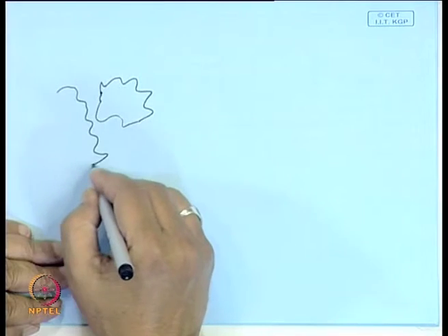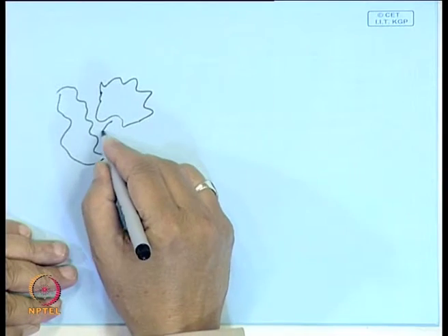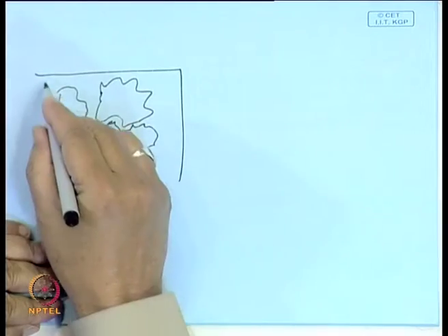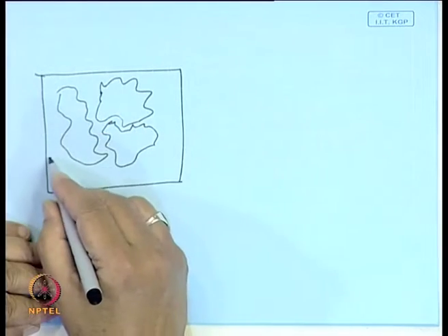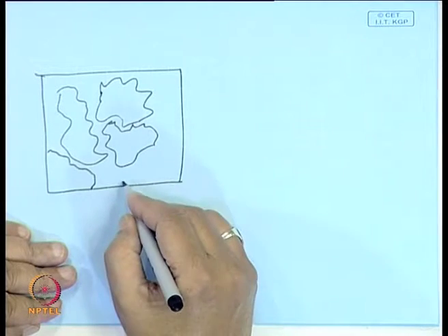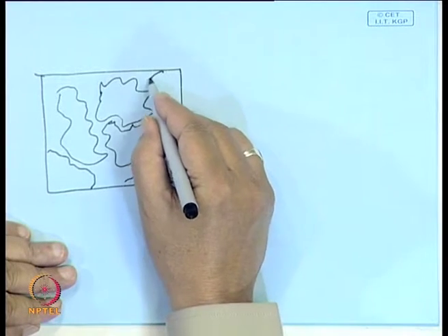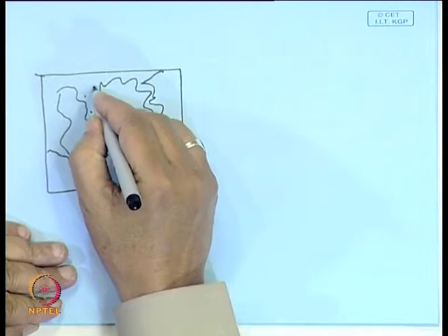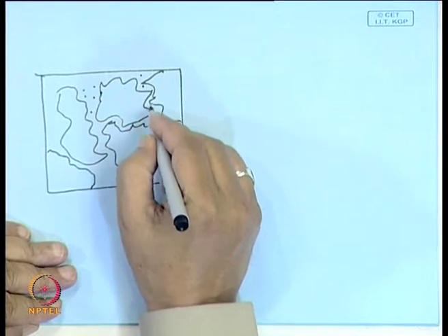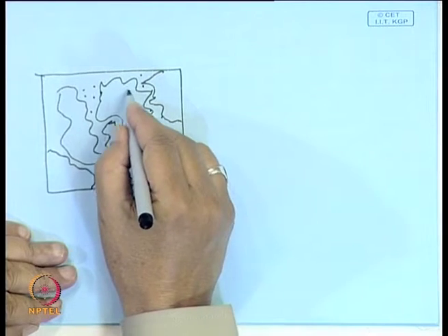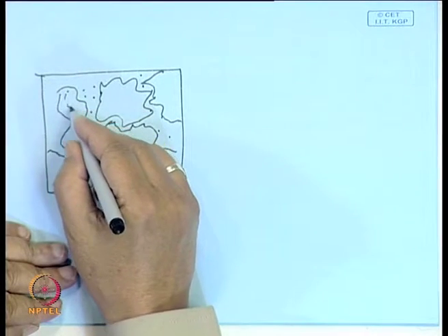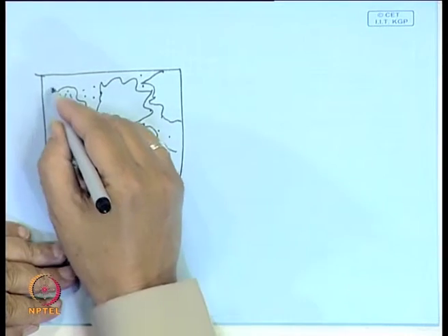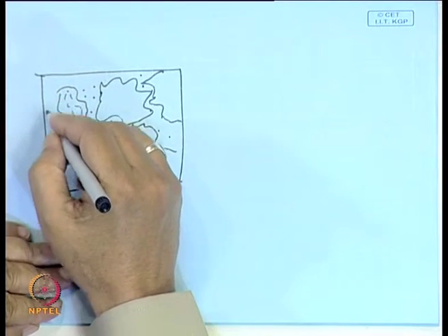There are different grains, and if you look at this structure of metal, you will find these types of dendritic grain structures and interdendritic channels. Often you have precipitates. Within this there is also a composition gradient. Sometimes there may be micropores here.